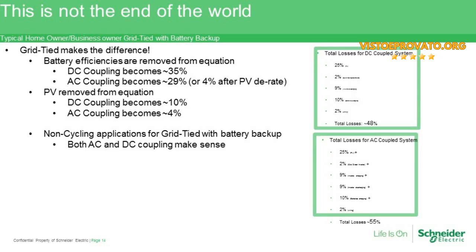But really that 9 extra percent or 11 extra percent that we're going to get out of a grid-tied system suddenly makes a lot of sense. So understand the needs of the customer, especially if it's a business where the loads are more of a bell curve and main power is consumed during daylight hours, then suddenly it may make more sense that a grid-tied and AC coupled solution again gives you that long-term investment and that return on that investment over the long haul. And I'm saying long because it's a long time before those numbers start to add up, but they do add up over time.